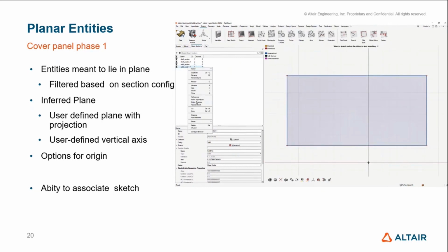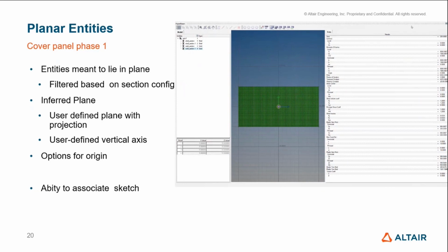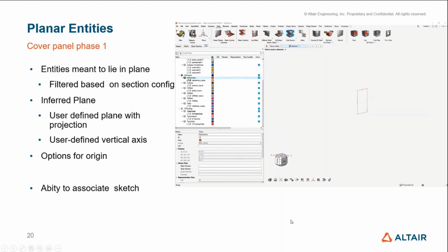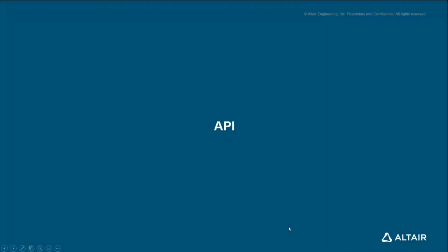So it was just to complete the demonstration for solid. What I wanted to mention is that in this case, we were using a beam section origin, which is slightly different from the sketch point origin. That's the third data name which has been added. No matter what sketch we use with a different origin, we can change where the beam section origin is in the section.